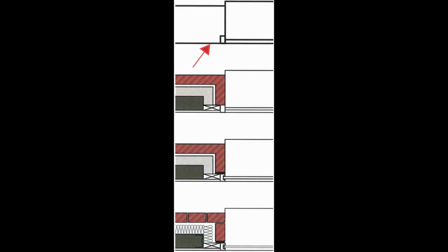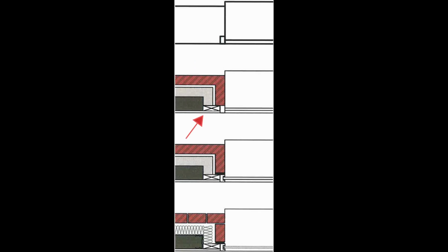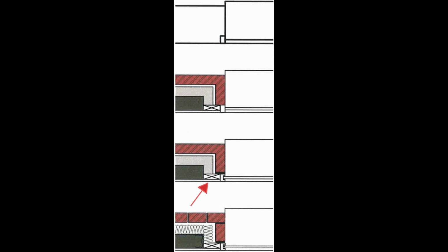Case study. In this example, the 3D geometry remains extremely simple across all views. At coarse detail, a symbolic representation communicates intent. At medium detail, wall composition and glazing thickness appear. At fine detail, additional construction information is revealed. At no point does the 3D geometry become unnecessarily complex. The intelligence sits in metadata and controlled 2D detail.